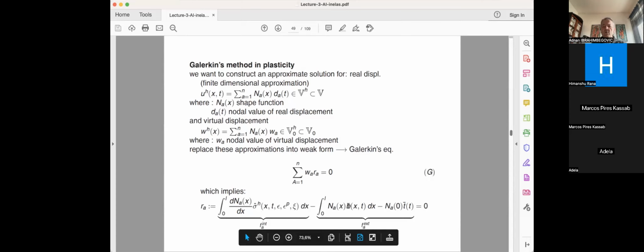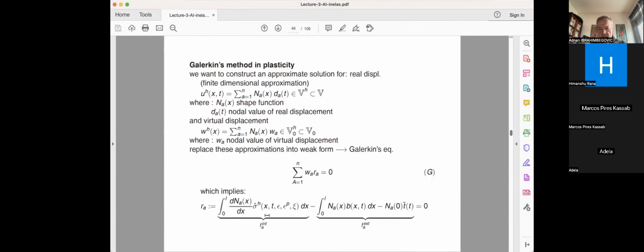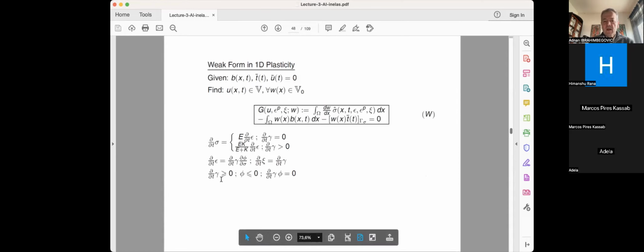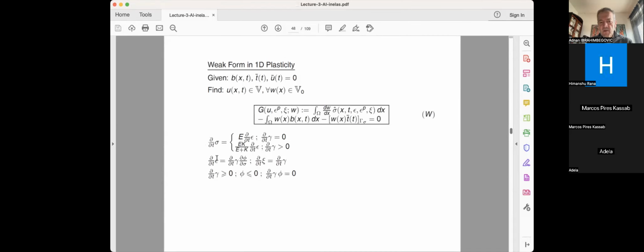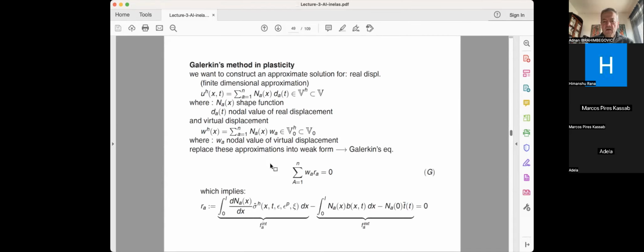So this time around, we obtained, again, not a set of linear algebraic equations. In fact, these are heavily nonlinear because the nonlinearity is hardening in sigma. And again, these are evolution equations. So we'll need an equation in time. So we'll need also the time integration scheme that we discussed for heat transfer. Namely, the time integration scheme comes from basically evaluating the time variation of these internal variables, plastic strain, which is missing here, and the hardening variable.